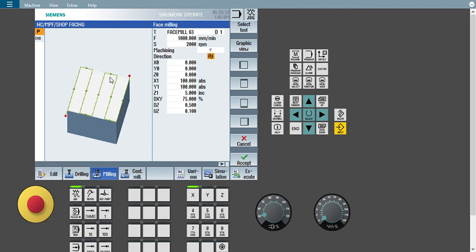The reason is that the machine is simultaneously doing up milling, down milling, up milling, down milling as per your machining condition. So zigzag cutting is always a good option for a higher material removal rate, and a unidirectional tool path is good for a higher amount of surface finish.